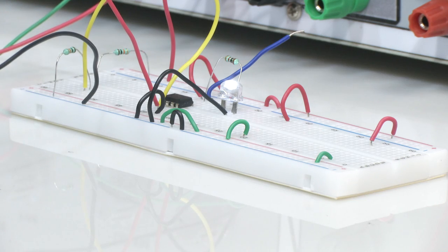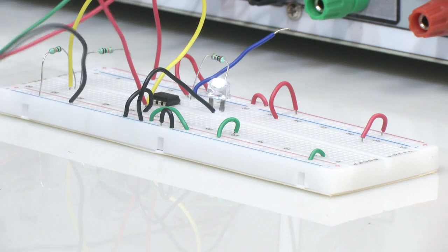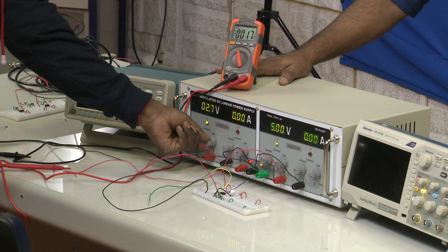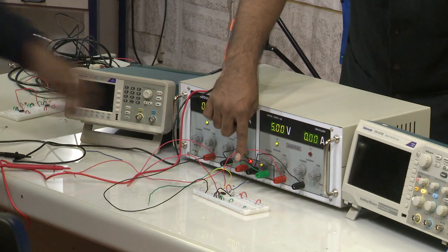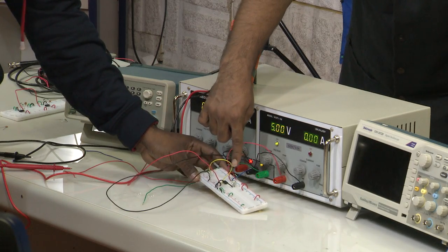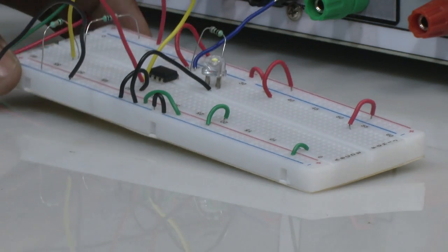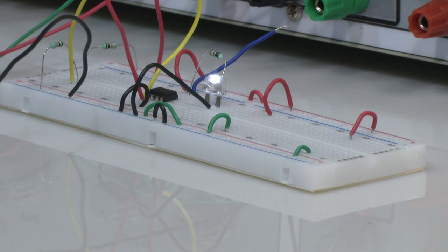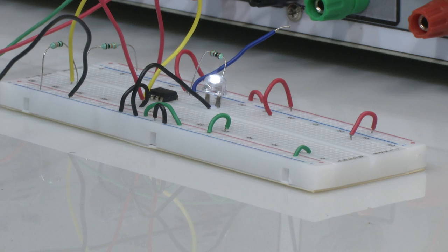Now, you can see here again, can you reduce the voltage please, so that students can understand. Reduce the voltage, you can see the DC power supply, he is reducing it to 2.4, bring it to 2.4, yes. Now, you focus on this one which is your LED, and you cannot see the LED glowing, right. Now, make it 2.5. So, at 2.5, now you see it is slightly greater than 2.5. As soon as it increases a little bit greater than 2.5, you will immediately start seeing the LED glowing, that means that the output is high, very easy to understand, right.